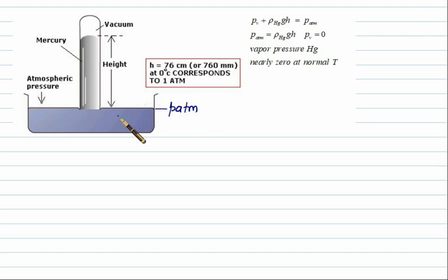If the pressure drops, then there is a chance that the mercury will boil off. If the mercury boils off, some vapor of mercury will be collected. So this one is the vapor form of mercury. All liquids will boil off at low pressure, and since the height is increasing, the pressure is decreasing. So we are attaining lower pressure. That pressure is known, that is equal to PV. Then you can start moving from this direction. So this pressure is equal to PV.